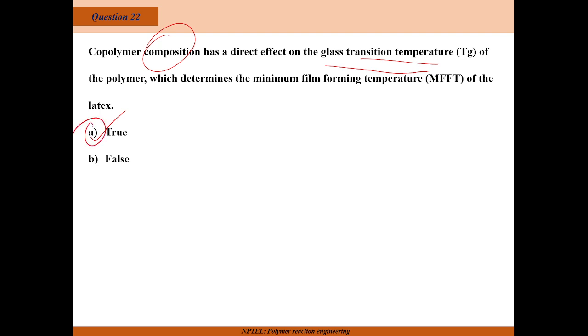Actually, I was relating how this minimum film forming temperature is related to Tg. I could not quite get the minimum film forming temperature. It refers to the lowest temperature at which latex, or some kind of adhesive, basically uniformly coalesces and spreads into a continuous film.